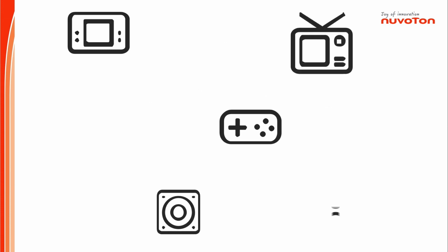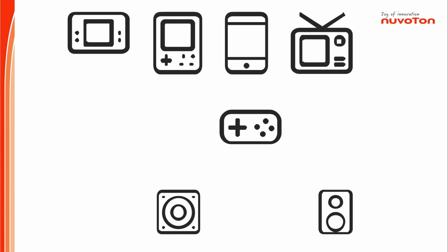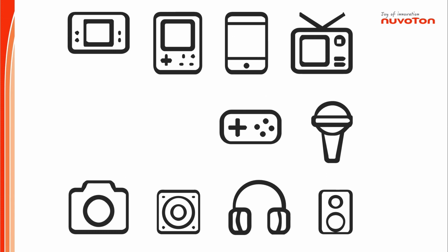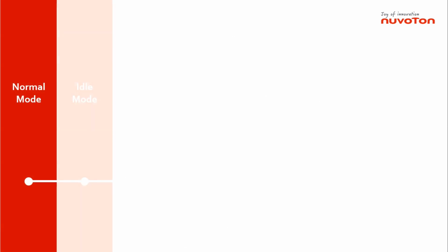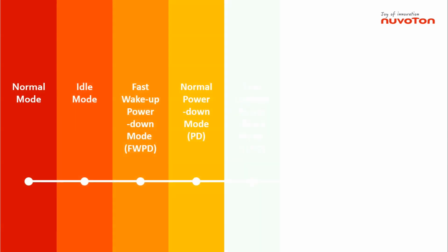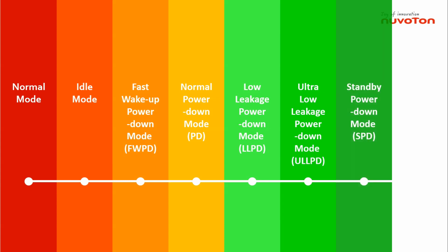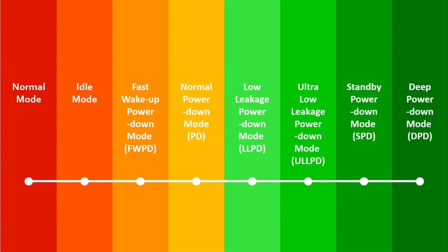As the size of devices is getting smaller and easier to carry, the devices require low power consumption and a battery to supply power for a long time. The M2351 series microcontroller provides some power modes. If the microcontroller does not need to work for a long time, you can set low power standby mode to save power and increase battery lifetime.